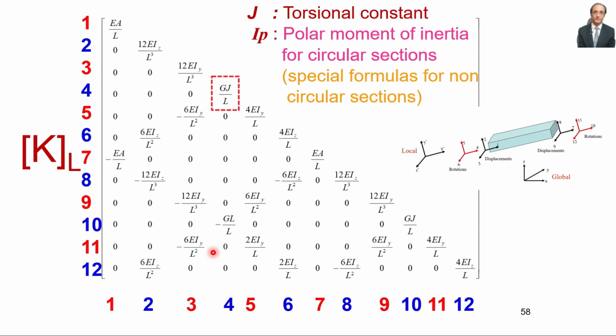Axial effects and bending effects were already considered independent in 2D analysis. In the 3D case, we have the presence of torsion. Again, our assumption is that we are considering 3D skeletal frames only. The role of the slab is only for vertical load distribution. The slab does not offer any kind of stiffness.